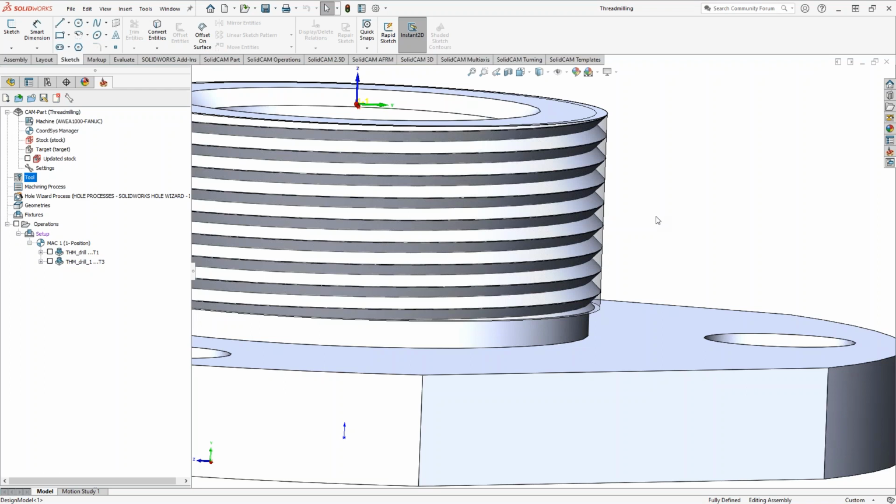Even maybe just go as far as, when you get your design model from your design department, suppress whatever cosmetic stuff they put there, and then you get that nice cylindrical face, and then you have a nice straight line for your thread milling toolpath. And then you can do Solid Verify, and then you can see your thread. But from the design model side of things, keep the geometry simple. Don't have this cosmetic thread.